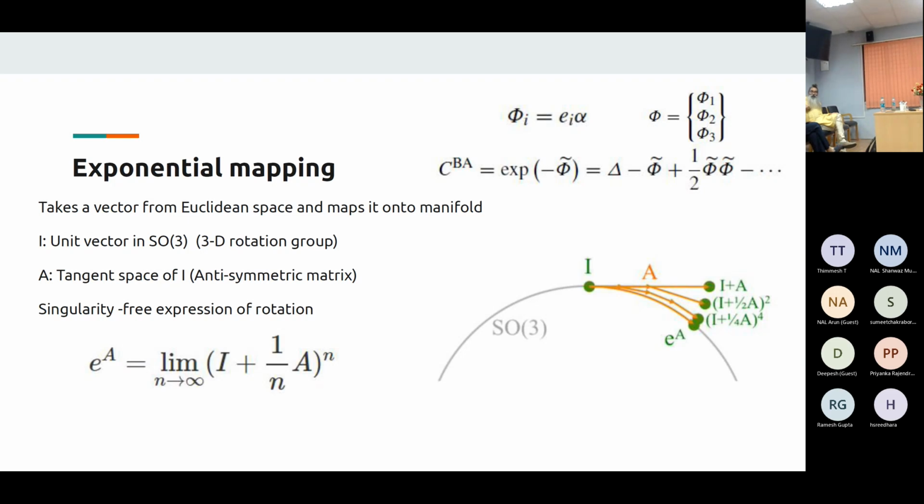But a curiosity came up: because you have a beam, you have a plate, will you have a shell? Yes, a plate is just a subset of this. In Cosserat-based theories, they use unidirectors, which are independent of the others, while FEM does a degenerate shell where everything else is in terms of the in-plane terms. In terms of VAM, initial curvatures are where it's captured. You just need to be mindful of what the variables are, in what form they appear, and identify the common things.